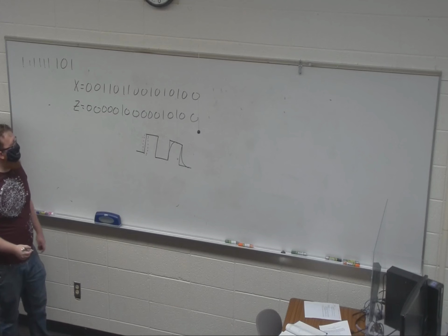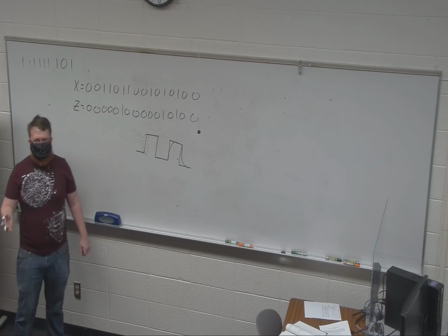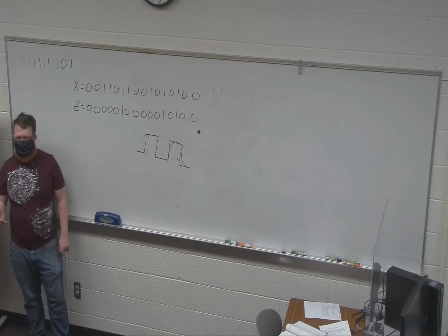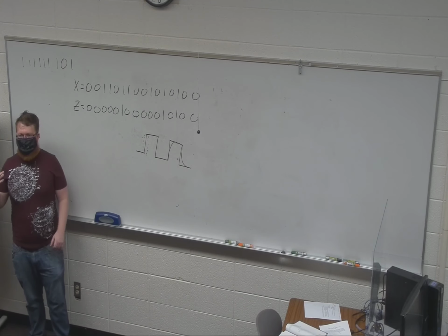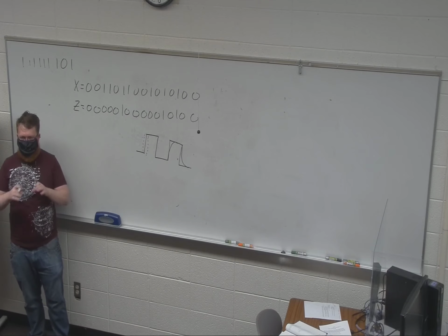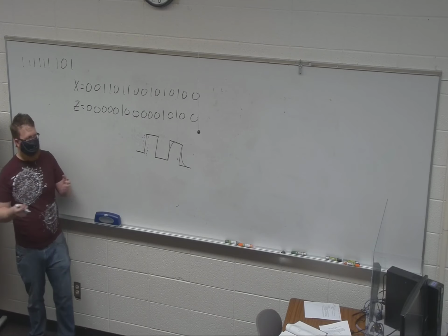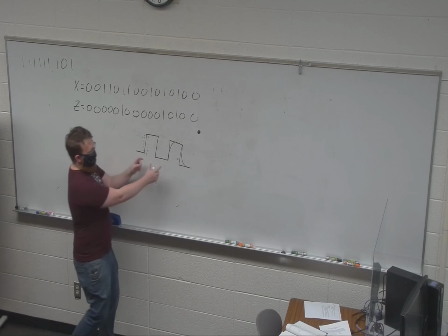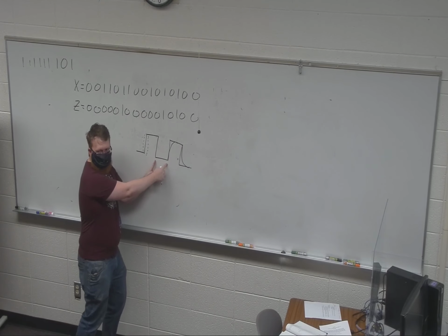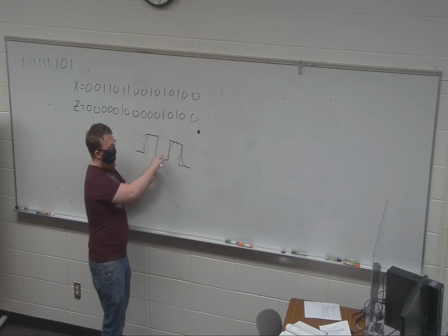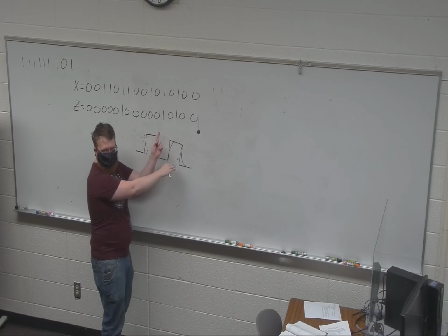The most extreme example I have of this is I was designing a camera system for a particle accelerator, and the way these cameras work is they have this big clock that essentially treats the negative voltage as a bucket to store charge, and then when the clock switches, it pushes all that charge from here into the next bucket.